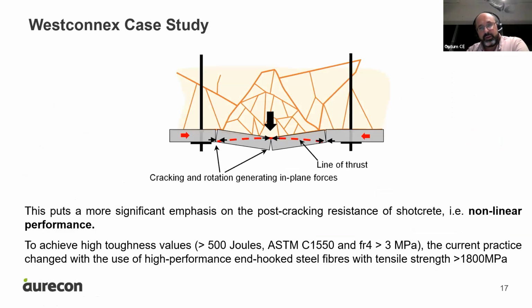And to also be comfortable with this, we wanted to rely on very high performing concrete mixes. For those familiar with fiber reinforcement, sometimes we talk in terms of toughness, or energy absorption. So we provided here some numbers for this type of test, which is the round panels, of 500 joules. In Europe, it might be more familiar with the EFNARC energy absorption, which is a different number. It's probably 2.5 times this. So the equivalent of 500 joules with our RDP, a round determinate panel from ASTM, will be equivalent to maybe a 1200, roughly, EFNARC panel.